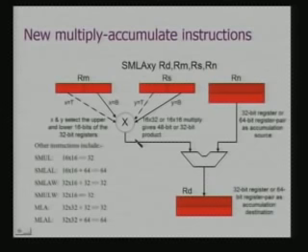This is just a part of the data path of ARM9E. In fact, 9E was obviously when we are talking about multiply and accumulate, an instruction required primarily for convolution operations, and it is an enhancement for DSP applications. So this is a basic data path enhancement. You have this multiplication taking place here, you get a 48-bit or 32-bit product which is added with a 64-bit register or a 64-bit register pair as accumulation source. So this data can be added with the result of this multiplication and stored here.